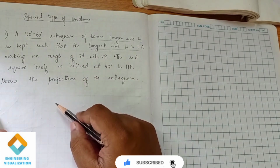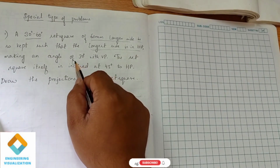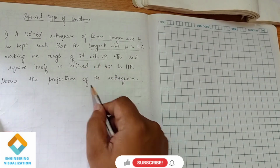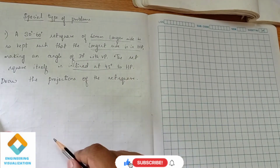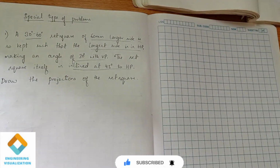So we have to keep the longer side in the HP plane, making an angle of 30 degree with VP, the set square itself inclined at 45 degree to HP. So we have to draw the set square. The main thing in this problem is we have to construct a set square. That's it. Other than that, it will be similar to your normal type of problem.